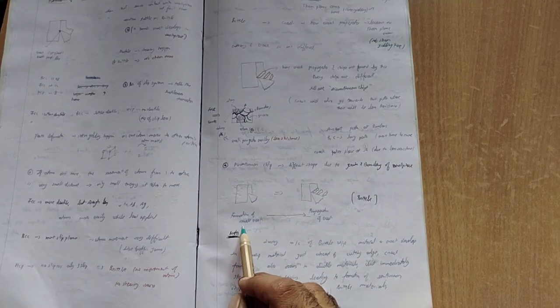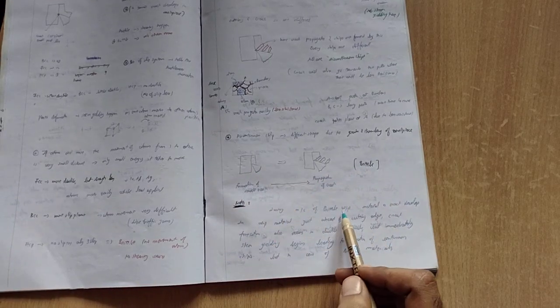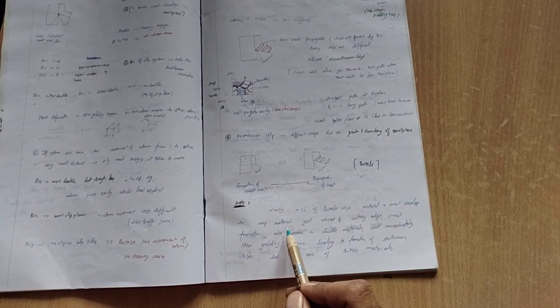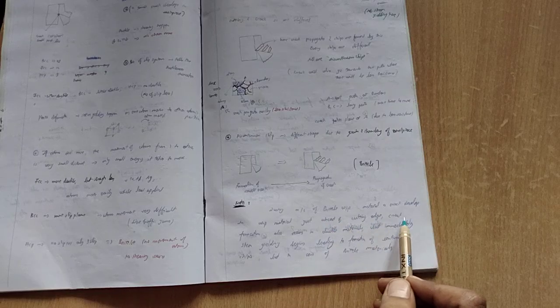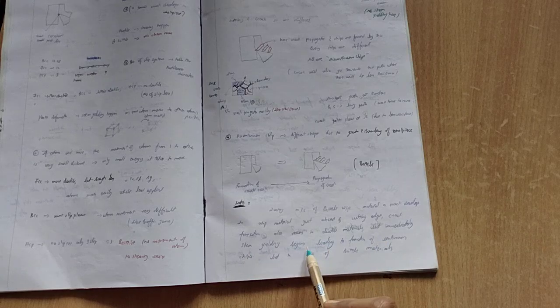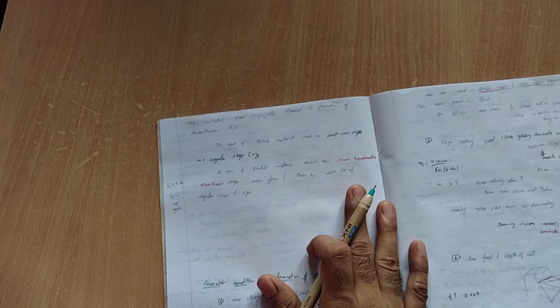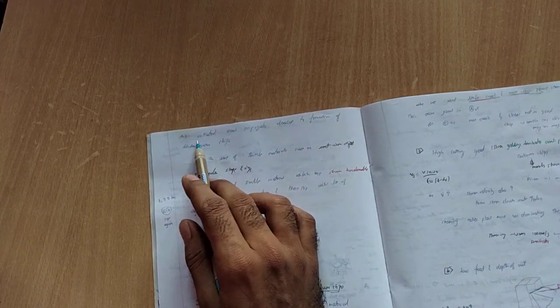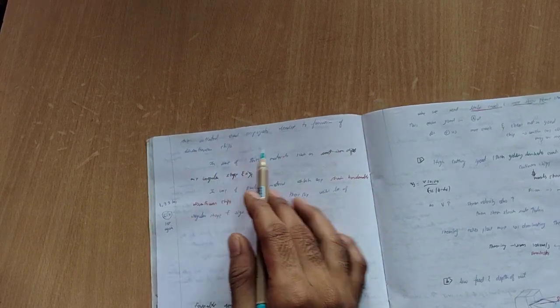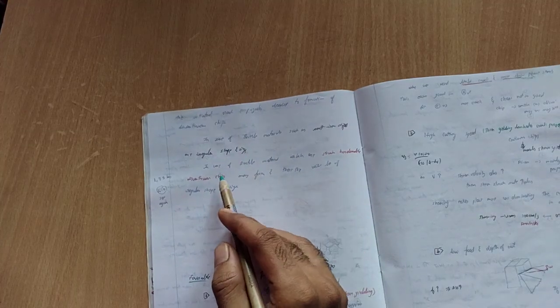So you can see formation of a small crack. Small cracks and propagation of cracks are generally brittle behavior. During machining of a brittle workpiece, cracks develop in the workpiece material just ahead of the cutting edge. Crack formation also occurs in ductile material, but shear yielding occurs immediately, leading to formation of continuous chips. But here that doesn't form. The initiated crack propagates before the formation of discontinuous chips. In the case of cast iron, the chips are irregular and different.